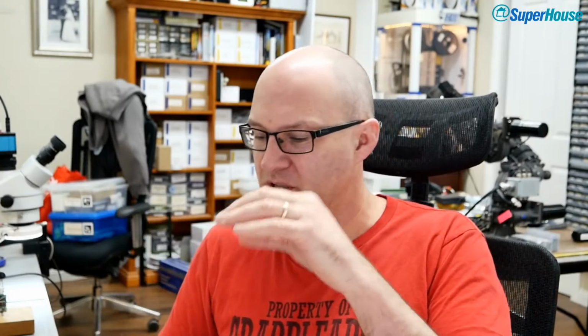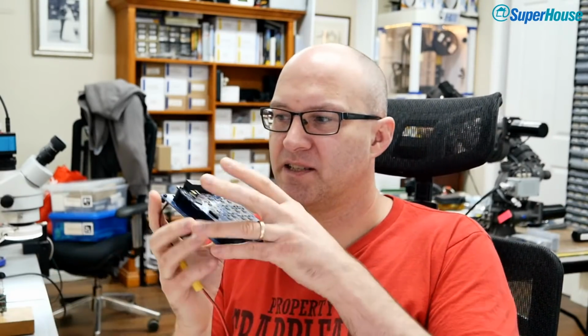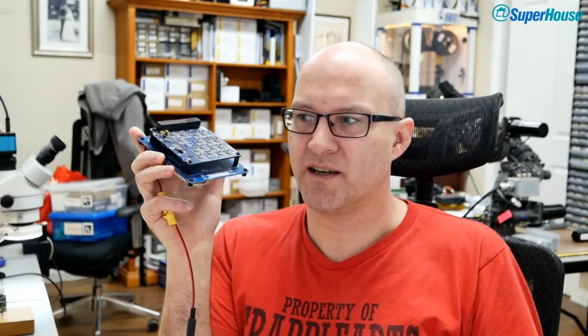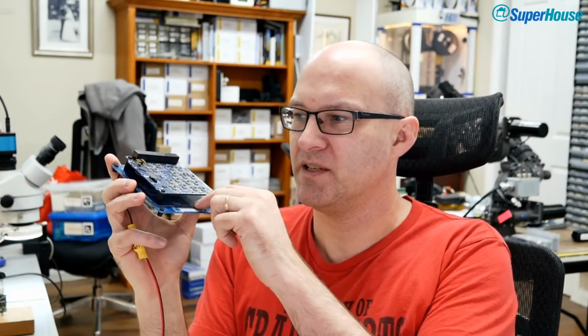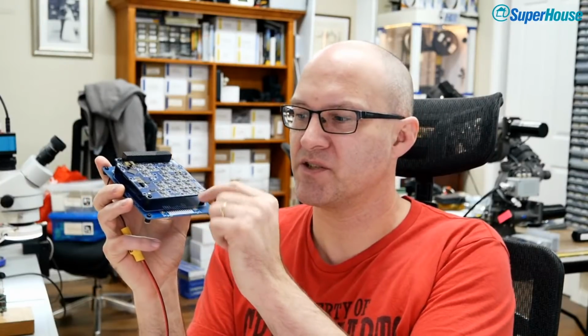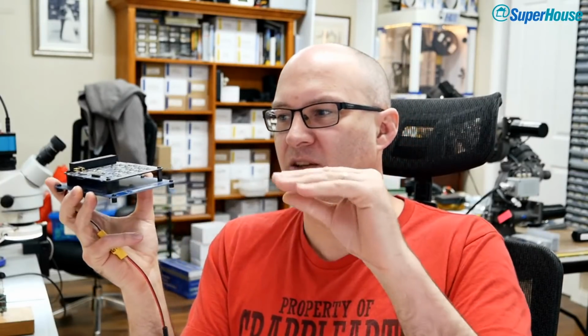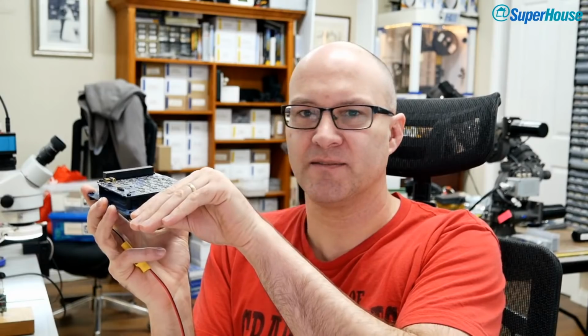Now the standard way of doing that, well there are a number of different options, but in this particular case it was a DB25 cable, so it passes through the wall of the vacuum chamber, plugs into your test rig, and on the outside there is a breakout that exactly matches the same connections. So what you can imagine is this goes inside the vacuum chamber. There would be, in the proper version that's used, a socket populated on the PCB, and the wiring harness just plugs into it.